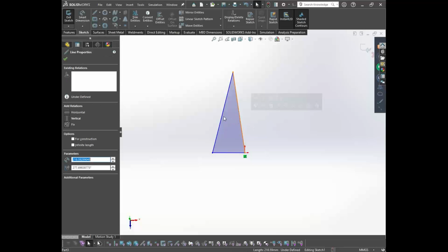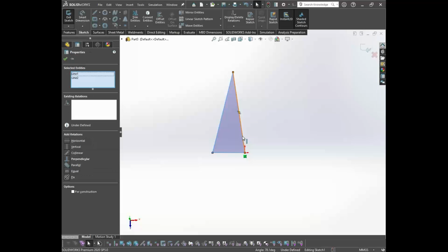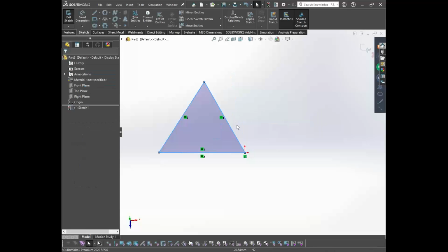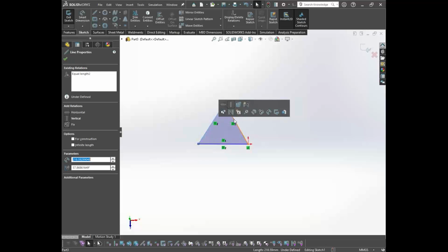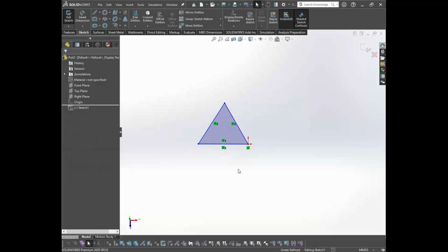Ideally, this aspect ratio should be 1. That is, all the sides should be equal. But while meshing, the solver will mesh it according to its needs. So we may not be able to capture these parameters always, but we need to make sure that we are getting close to the value of 1 as the aspect ratio. If I want to create a shell mesh, the sizes should be equal, so the ratio of maximum to minimum should be 1. This is what the aspect ratio means.